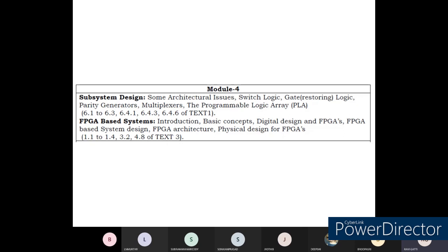One more important thing we discussed is the control path. It's not that all the elements will be multiplied or added successively. Sequential operations will take place in any circuit implementation. So the signaling mechanism, or controlling of each operation from the fundamental units, we need to do. For that we will be using control signals, that is nothing but a control bus. Then we went for the ALU design, or implementation. There are different varieties of ALU implementations we have done. In that ALU implementation, we discussed the adder circuit, that is nothing but the implementation of a half adder.